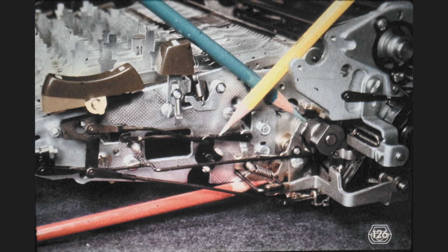During the printing operation of a low-velocity character, when the second scribe mark on the cam, above and to the rear of the green pencil, is aligned with the mark on the cam follower, the low-velocity selector latch should clear the lug on the tail of the cam follower by 0.25 millimeters.